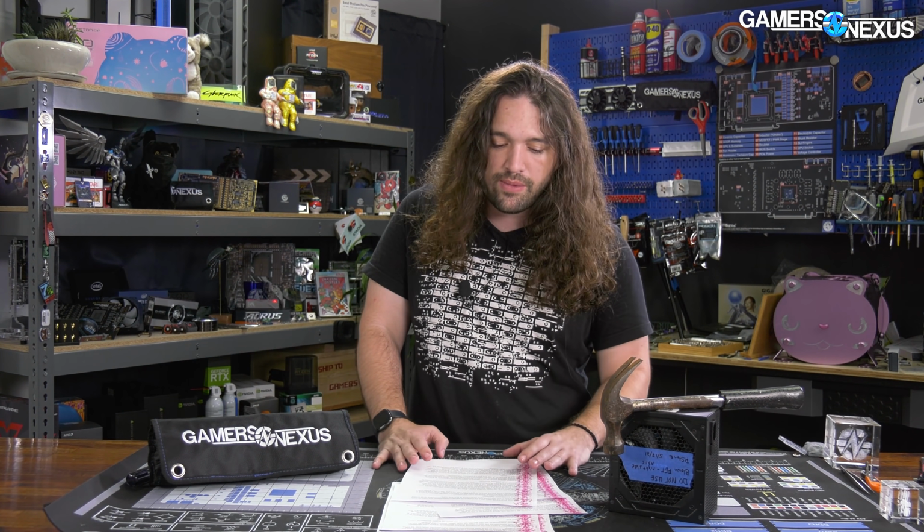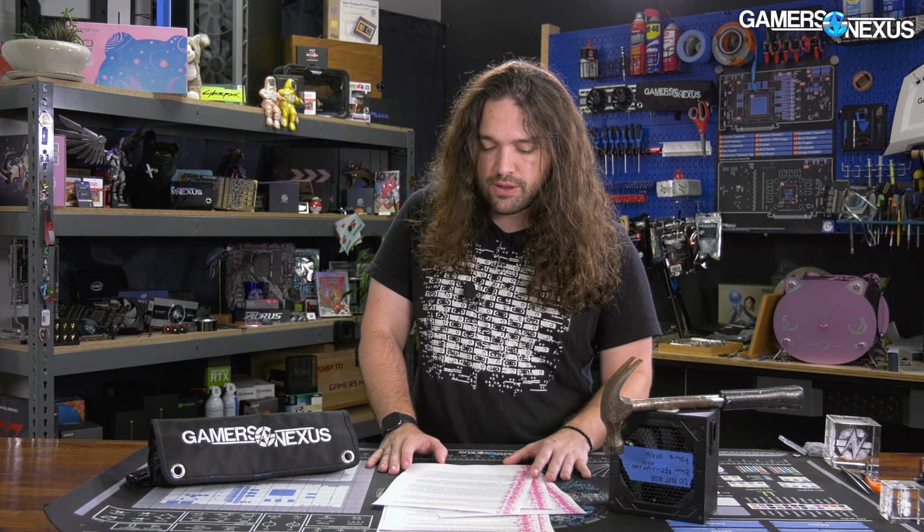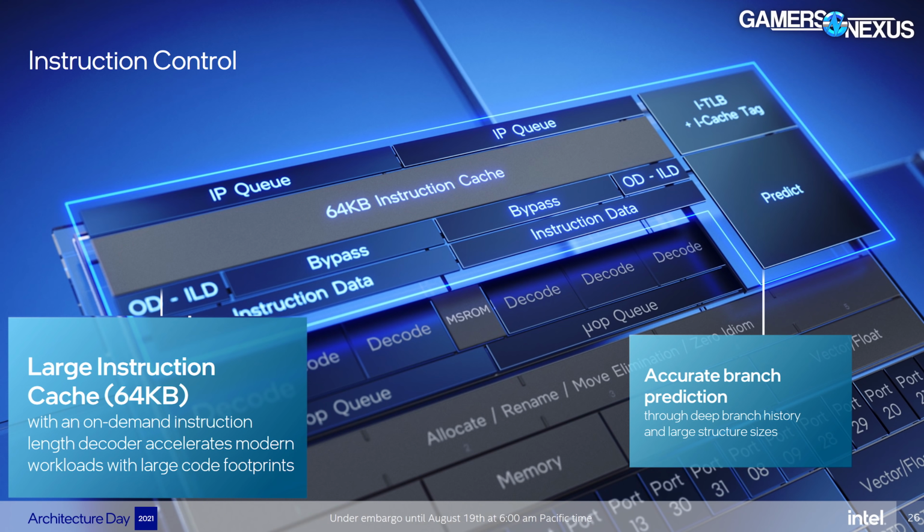Most companies describe this by saying, well, most users will upgrade from even older hardware than the last 2 years, which is true, but also from a benchmarking standpoint, the percent gains we will see will be largely judged on the most recent generation. So keep all that in mind, and obviously we'll be able to talk about that when it comes time to test them. Continuing with the instruction handling portion, there's an on-demand instruction length decoder, or ODILD in this image,